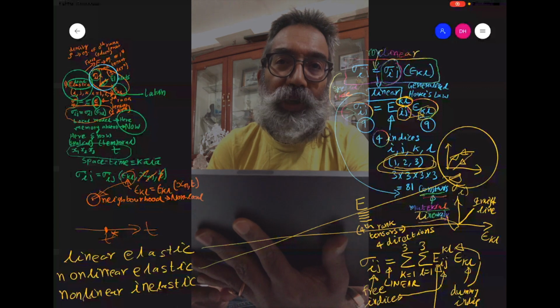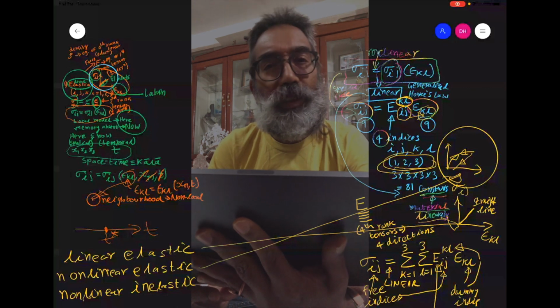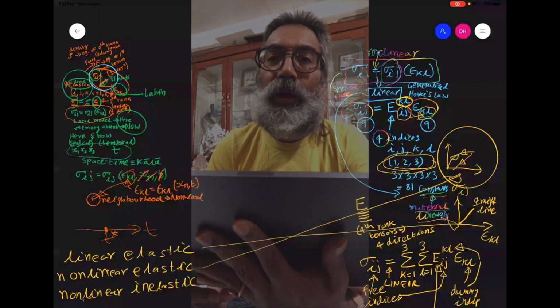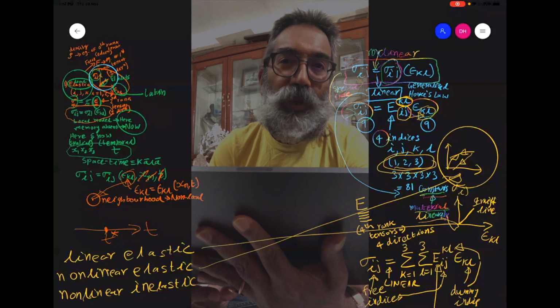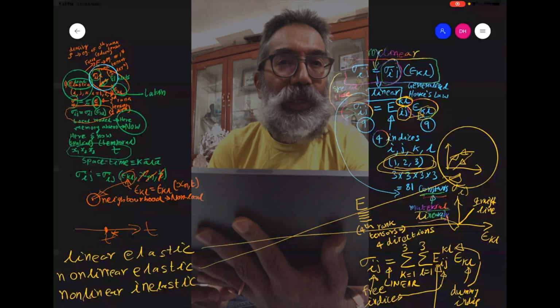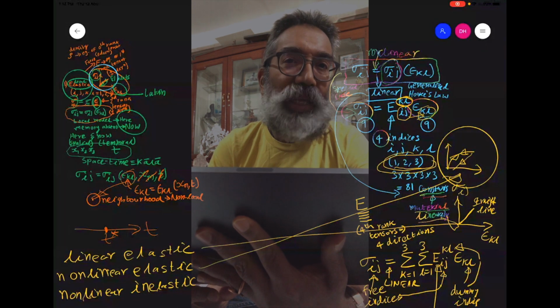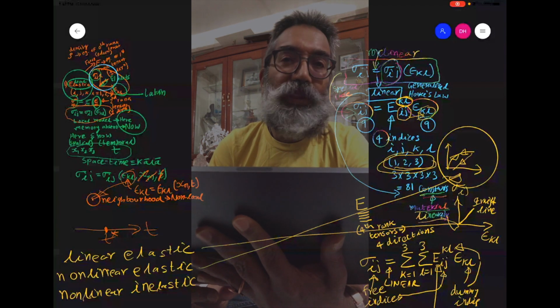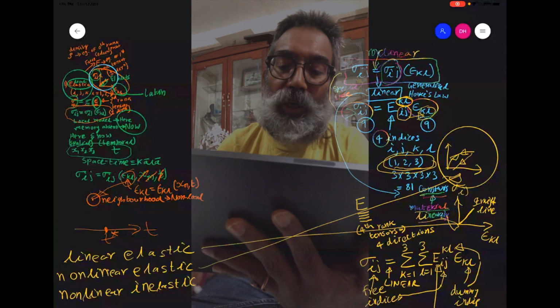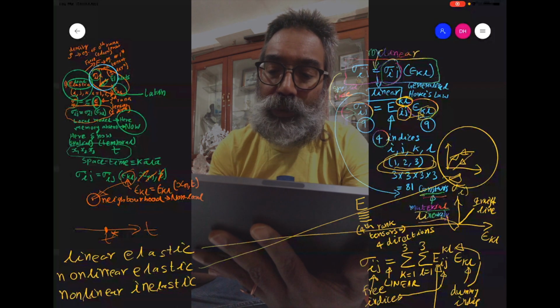It will be very different at high strain rate as compared to a low strain rate, and various other things like what thermal cycles it has gone through, and therefore does it have any creep, what mechanical or thermal loading cycles it has gone through, and therefore what is the fatigue, and therefore what is the remnant strength that it has, which will limit how far this can go.